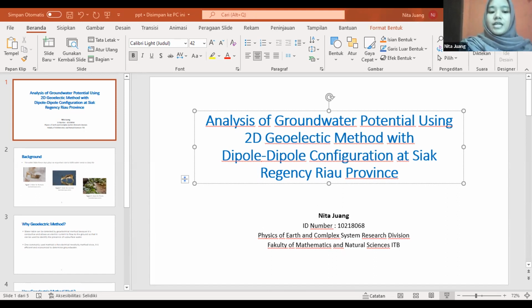The electrodes consist of two current electrodes, C1 and C2 in figure 4, that deliver the electric current, and two potential electrodes, P1 and P2, reading the potential difference after the current passes through the rocks. The four electrodes are plunged into the ground at a certain distance. The longer the distance of the current electrodes, the deeper the rock layers the electric current can penetrate.